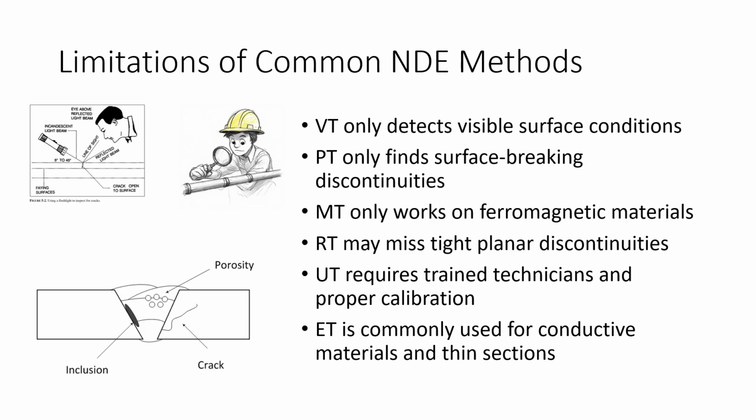And then eddy current testing. We use that for conductive materials and thin sections, and we're not using eddy current testing to find a defect in something that's 9 inches thick. You have to understand what your process can do and how you can utilize it.